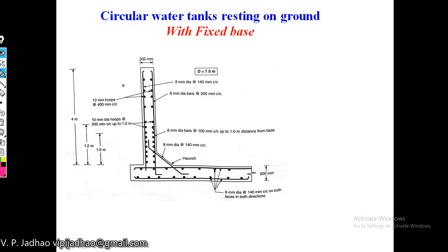Now, as per our previous experience while designing any water tank, it is considered that if this is the water pressure which is acting on the water tank wall, this intensity will be gamma into h. So this water pressure is acting, and it is considered that the cantilever action due to the water pressure